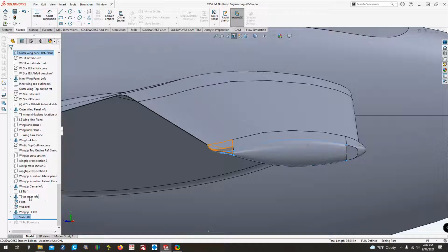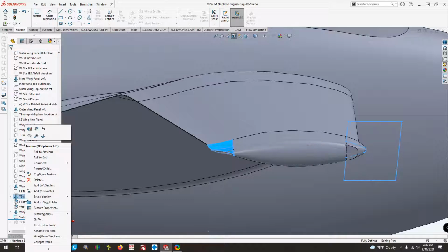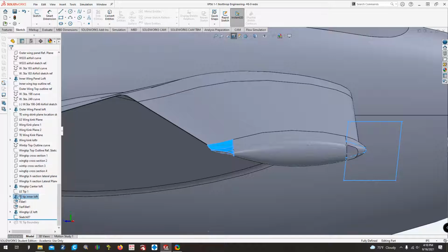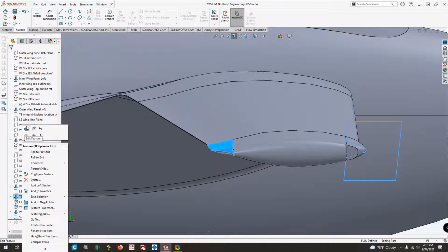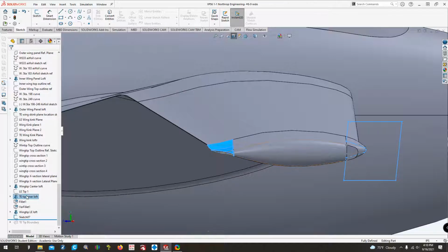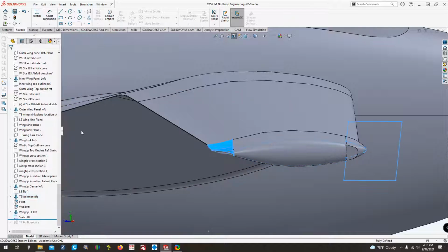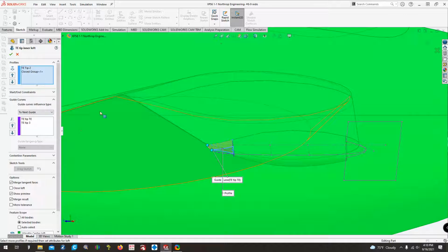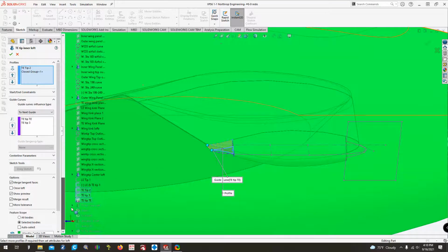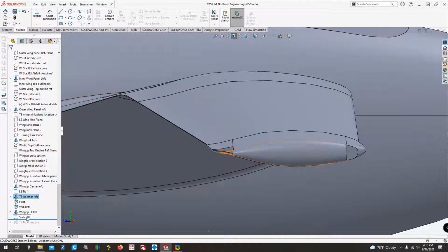Let's save it, because this loft here, I'm actually going to delete now. Actually, I might not have to. Yep, I'll have to delete that, because if I try and just insert this sketch to it, watch, you'll see what happens. It most likely won't work. Yeah, see, the sketch is not available because it's below the feature tree. The feature tree being all of this information. So in order for us to be able to use this sketch, we'd have to drag it up, but you see we can't do that.